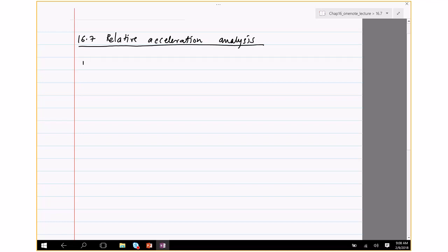What you have to be able to do before you actually solve problems related to acceleration is remind yourself that if you want to find the velocity of B, you have to find the angular velocity before you can solve for angular acceleration: vB is vA plus omega cross rB with respect to A. So you would need that before you can solve for accelerations.